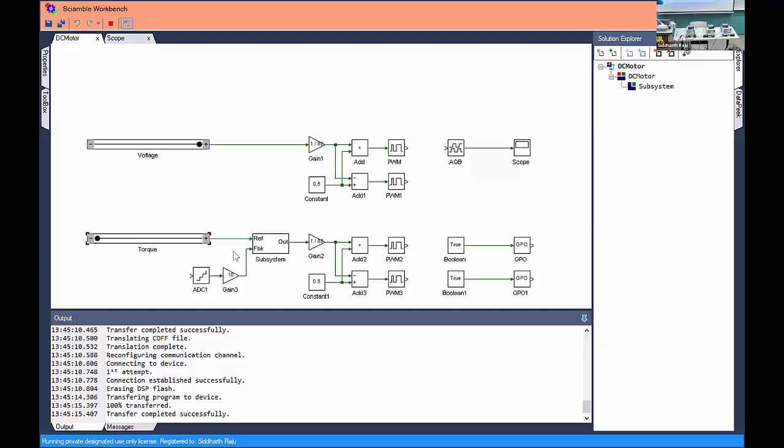When the current increases, since this is a whole bunch of copper coil, the drop in the resistor of the coil also increases. Right? The voltage dropped in a coil resistor is going to be IR. So whenever the torque increases, the current has to increase in the motor. And we have already seen the formula, right? Force was B I L, or I times L cross B, whichever convention you like.